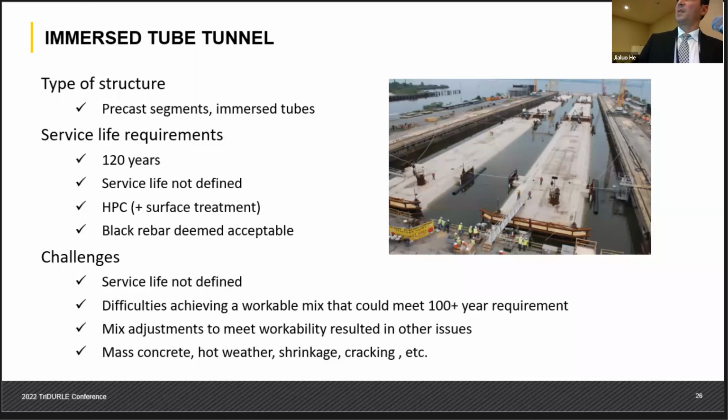The high performance concrete plus surface treatment could be used. So in this case, they were allowing the surface treatment to be accounted for in the service life. And then black rebar is deemed acceptable. Now, when you allow black rebar, you don't have a rebar that is corrosion resistant. So all of a sudden you need to manage your cracking better, right? Because once you allow cracks, then you're going to have completely different issues to manage, right? So it was a little bit challenging.